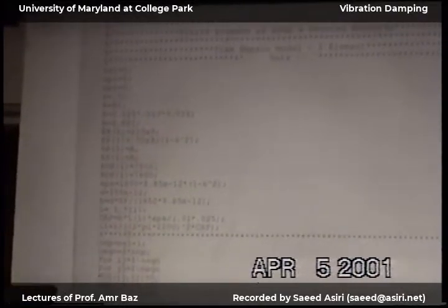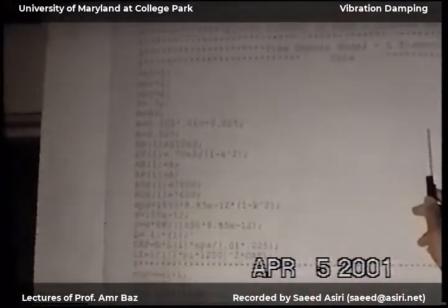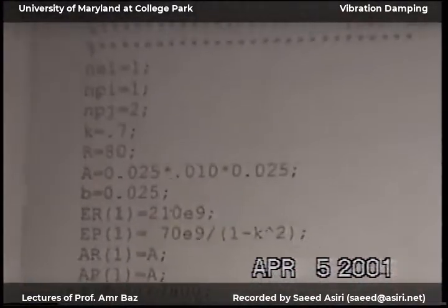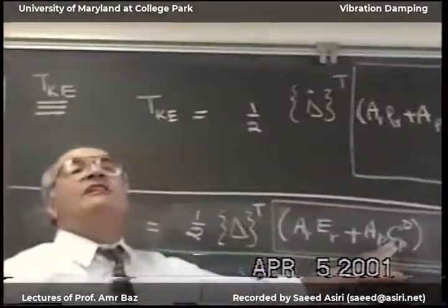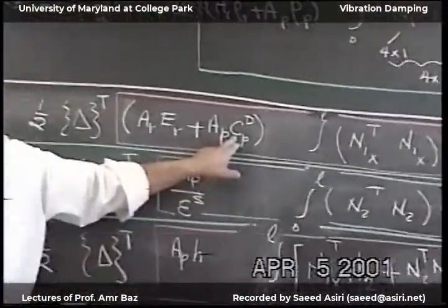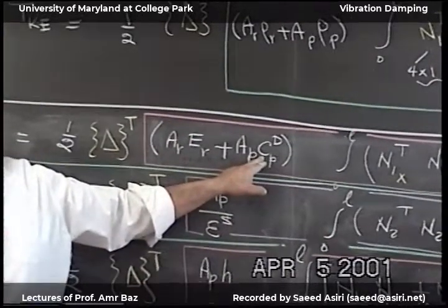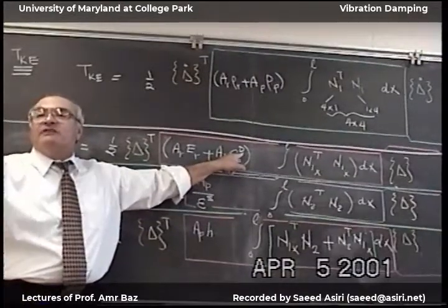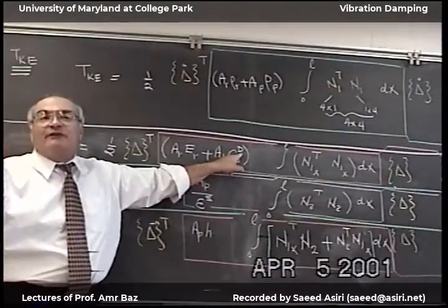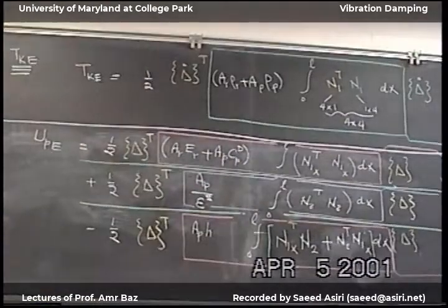The most important thing is, for example, here, Young's modulus of the material. Young's modulus of the piezoelectric material is here when it is open circuit. When it is open circuit. Young's modulus that we get for the regular material, C, E, when it is short circuit, are completely different. The factor that combines them is the electromechanical coupling factor.